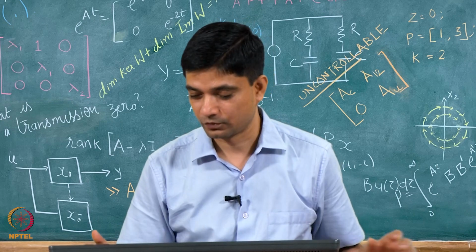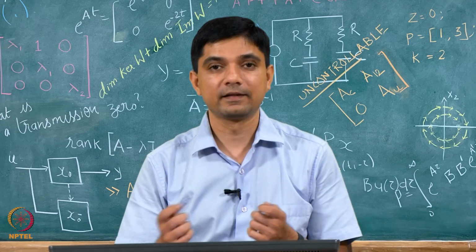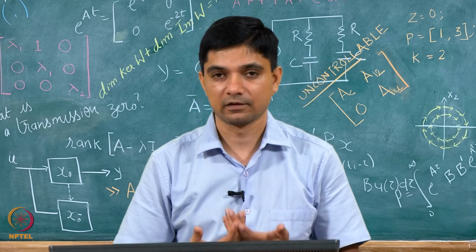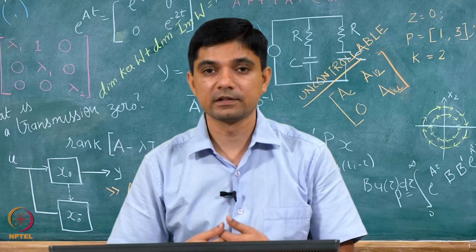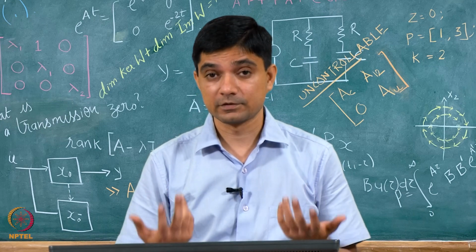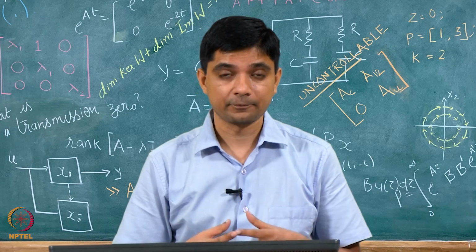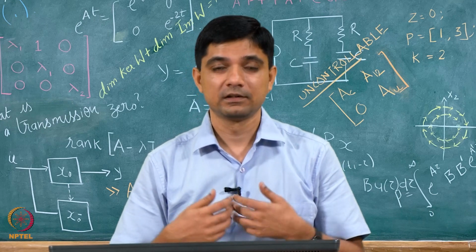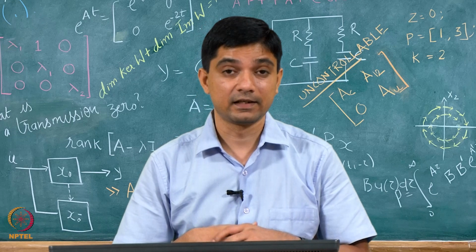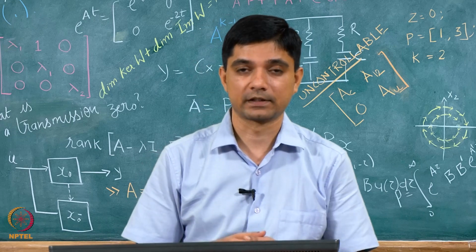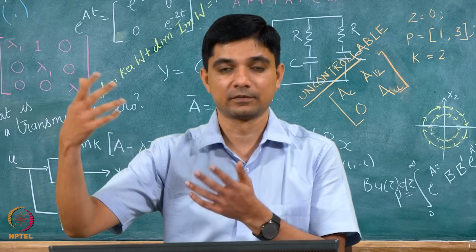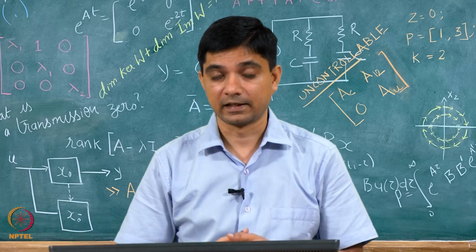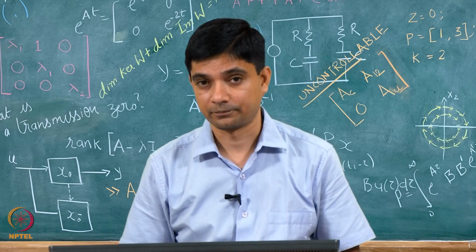So, it will be some 0.4 or things like that. So, we can just play around with the quantum of delay and check whether or not the system is stable. So, what is the observation here? Even though there are some systems which are stable independent of delay, some systems are stable depending on delay. For some small values of delay are acceptable, say in this case 0.4 seconds, but for larger values my system goes to the verge of instability. So, this is a little better result than what we had previously, right.